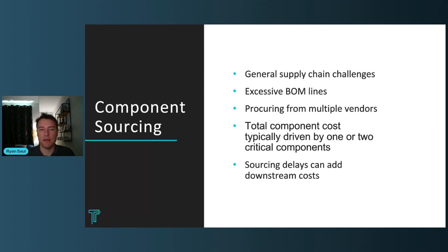So I would keep in mind your target unit cost at production, and use that to inform your component choice when you're designing your functionality. Even if you're only going to low volume production, even if you're going to hundreds, not thousands or hundreds of thousands, we often see individual components fundamentally define the bill of materials cost.